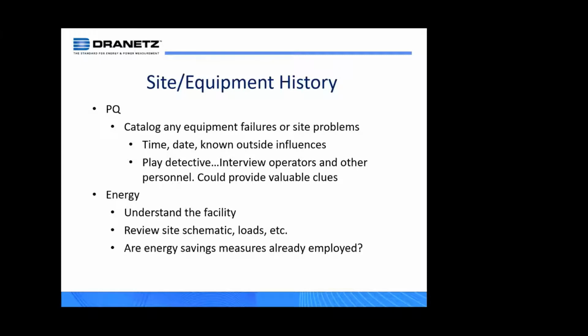And this is also an important aspect as well, PQ. People ask me all the time, how do I know if I have a PQ problem? If you characterize or catalog any time that you have a failure, if you're in the middle of your work process and the lights flicker, just note the time and date in which that occurs. Because for power quality troubleshooting, your attempt is to draw what we call a consistent correlation.